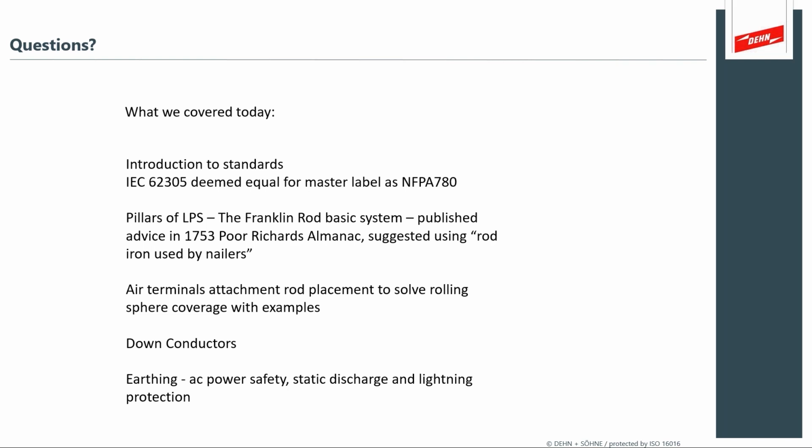Yeah, legacy structures. Then can we use an oil tank body, a properly bonded and earthed oil tank body, as the down conductor, or an HVI kind of conductor as shown in the DEHN literature?